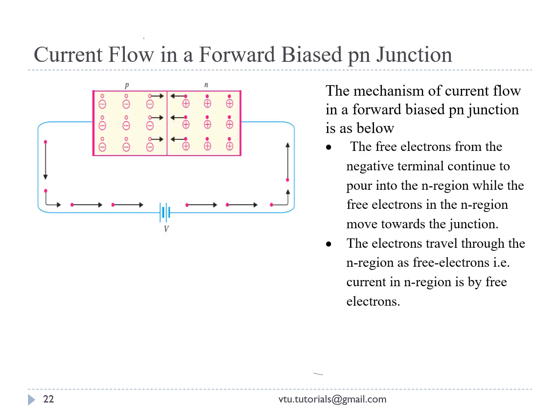For the operation of the semiconductor device, the junction is to be present in the forward biased condition. So now let us see the current flow in the forward biased condition. We know that in forward bias, P type is connected to the positive terminal of the battery and N type connected to the negative terminal of the battery. So this applied voltage will be in the opposite direction to the depletion barrier potential. So that way this voltage will overcome the barrier potential.